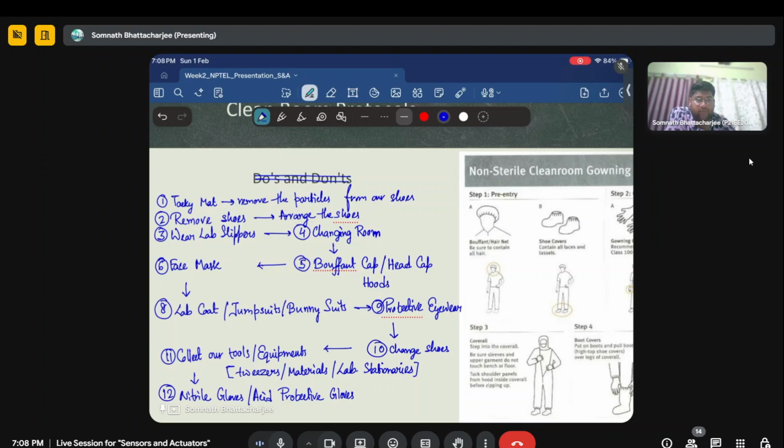In most cases, if you are fabricating some devices or characterizing devices, you need to stay away from several volatile materials as well, and also from contaminating the device itself. So you need nitrile gloves. In most cases, I use nitrile gloves. These are all for dust avoidance. So let me write it down as well, to avoid some kind of dust. And after these things, you are able to completely enter into the clean room itself.